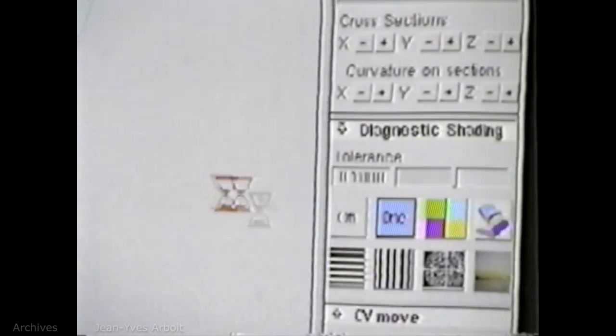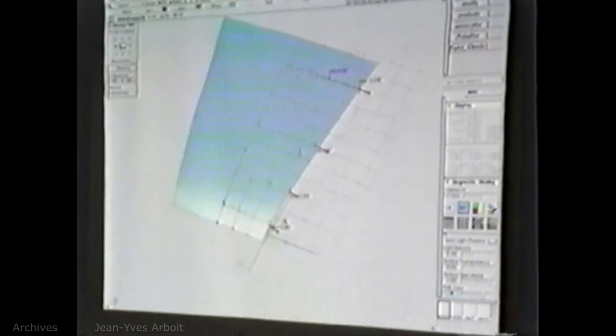is even. So right now, as I look at these, they come to a peak, and I'd have to modify these by going in and choosing CVs, and actually modeling it. This wants to be normal. There. That wants to be, so it's an even acceleration across center line. But that's one of the finer points of trying to make a nice looking surface. So we can have symmetry across center line both visually and enforce it with tangency.